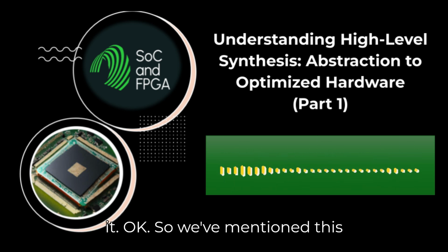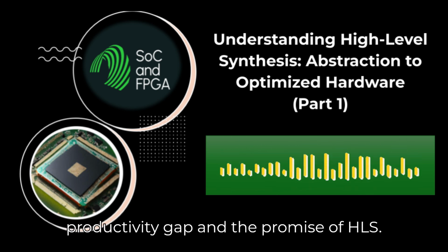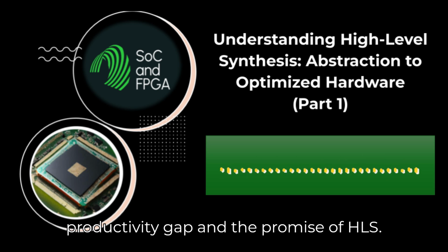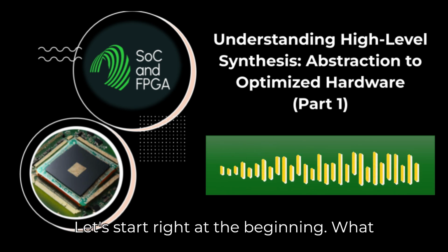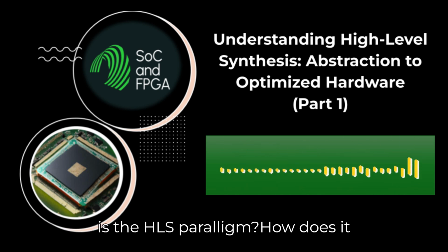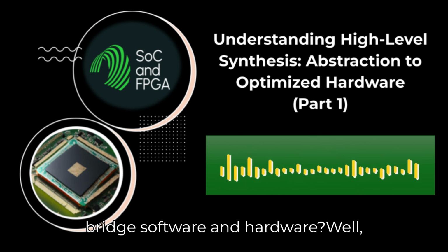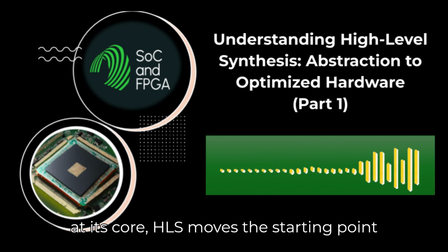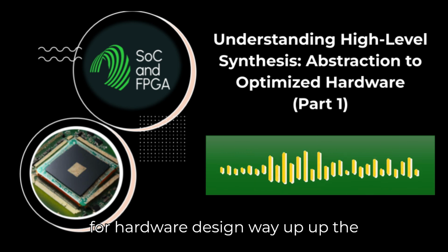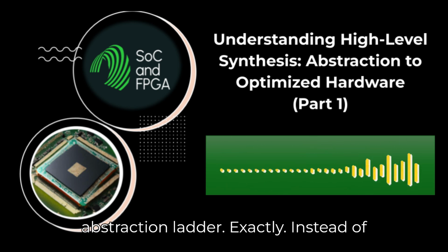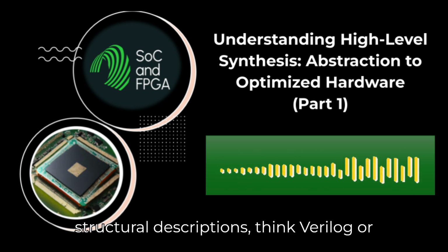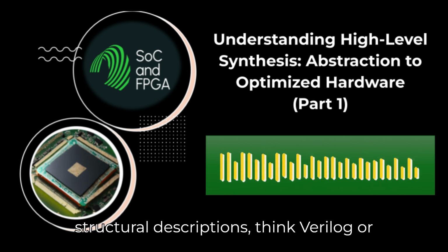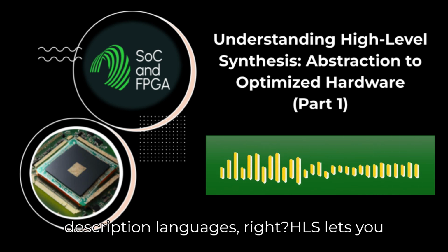Let's do it. Okay, so we've mentioned this productivity gap and the promise of HLS. Let's start right at the beginning. What is the HLS paradigm? How does it bridge software and hardware? Well, at its core, HLS moves the starting point for hardware design way up. Up the abstraction ladder. Exactly. Instead of grappling with those really low-level structural descriptions, think Verilog or VHDL. The traditional hardware description languages?